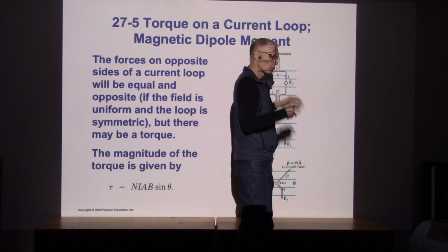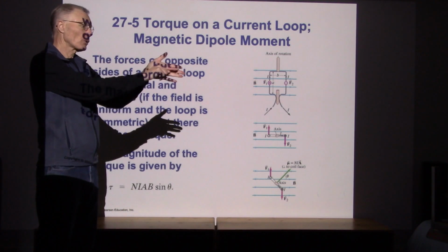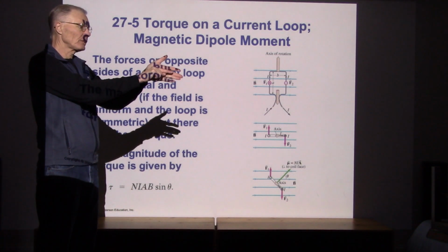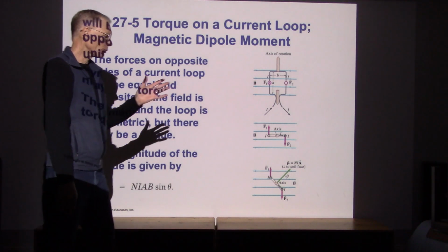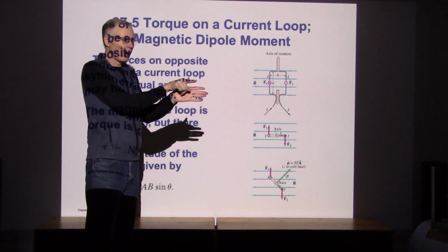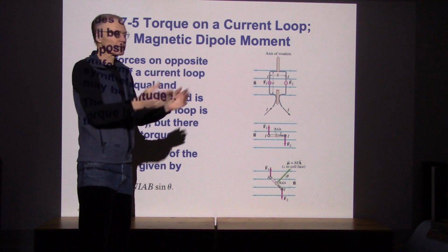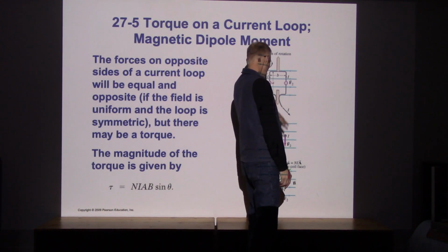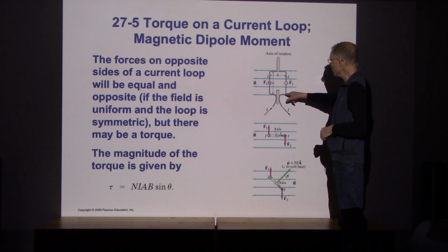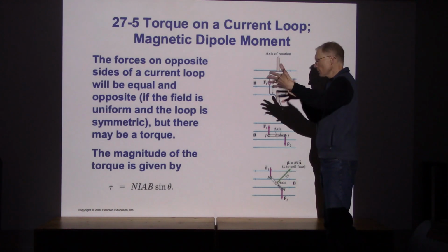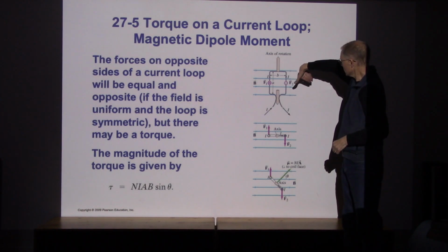What happens when the current turns and runs along the magnetic field? Now, I don't know if we've mentioned this very clearly, but if I've got current going through a magnetic field and the current runs right along the magnetic field line, it doesn't experience any force. It's that sideways effect again. In order to have a force, I need to have a current where at least one component of its direction is not lined up with the magnetic field. So lining something up with the magnetic field doesn't give us any force. At least with this diagram we have right here, and there's some more diagrams below we'll have to compare with, looking at this diagram right here, there's no force along the top. There's no force along the bottom. Where the current's moving upwards, there's a force into the page. Where there's current going downwards, again using a right-hand rule, that looks something like this.